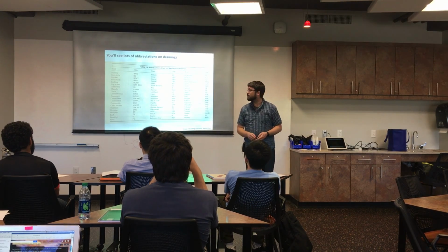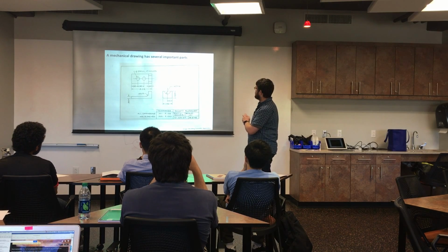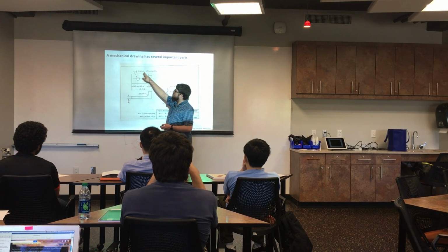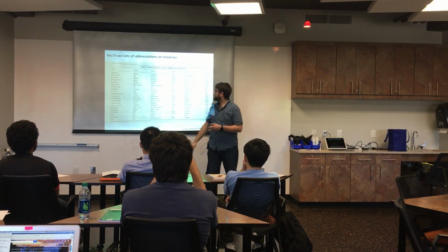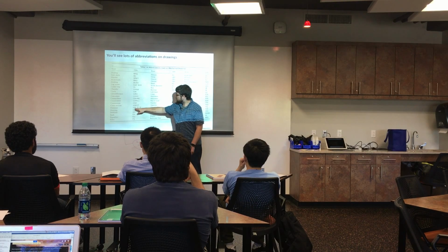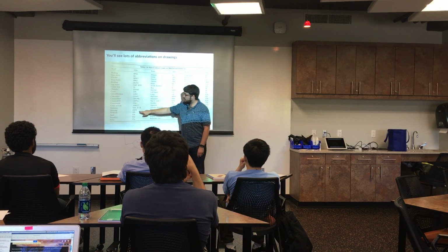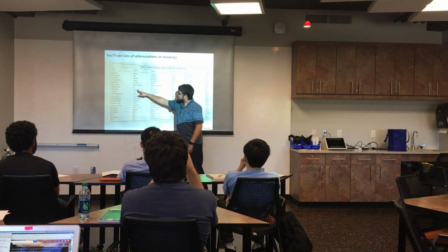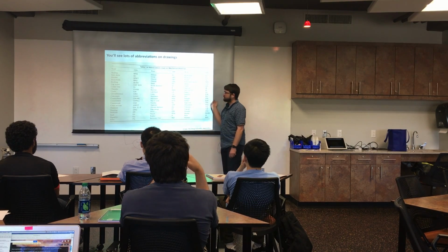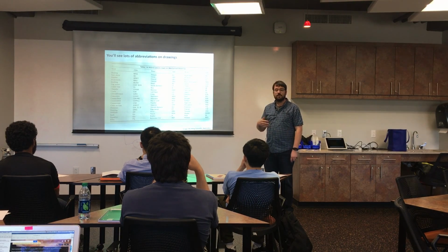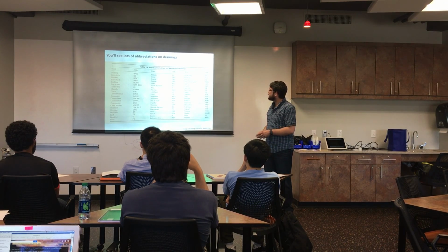And there'll be a lot of markings. On this one they actually didn't use too much jargon. For example, here they actually said 1/2 drill, 2 holes. But you'll see these on a lot of drawings. So DIA or D or an O with a slash through it, for example, is a diameter. Chamfer, CHAM. All of these you'll see, and this is a handy table I put in the slide so you can go look stuff up on it if you need to make a drawing, or if you're looking at a drawing and don't understand exactly what something means.